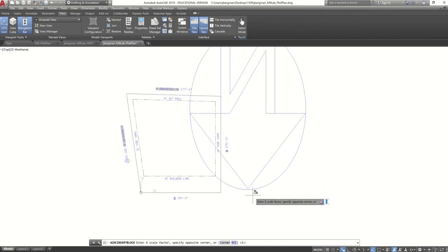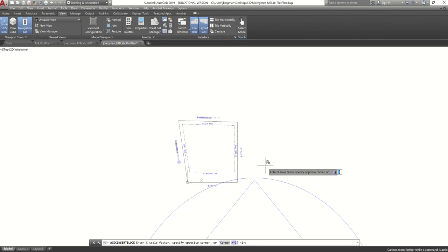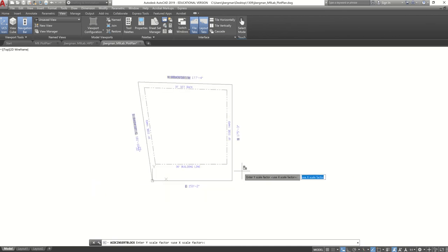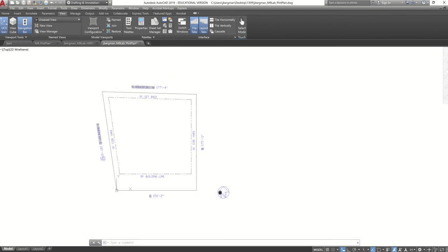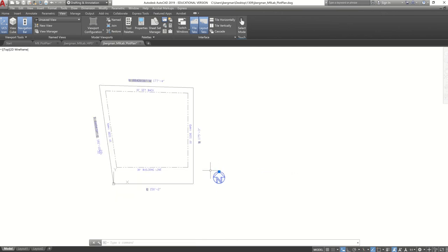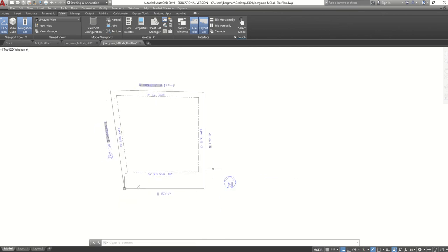And then, because I said I was going to specify the scale on the screen, the scale is going to be 10, enter. Y scale 10, enter. Okay, so I kept it the same shape, so I did 10 and 10 for both of them. I'm just going to show you guys a different way to do that as well.